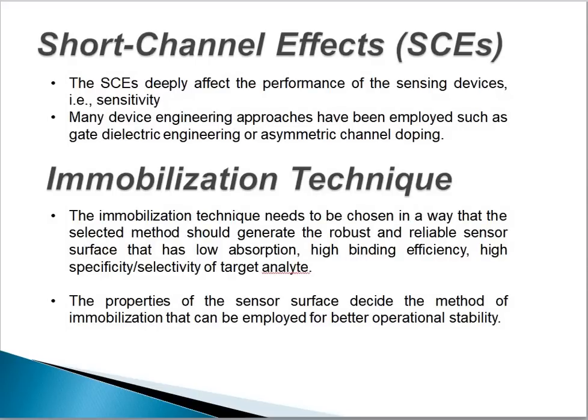First one is the short channel effects. The short channel effects deeply affect the performance of the sensing device, mainly sensitivity. Many device engineering approaches have been employed, such as gate dielectric engineering, or asymmetric channel doping in the case of TFET.